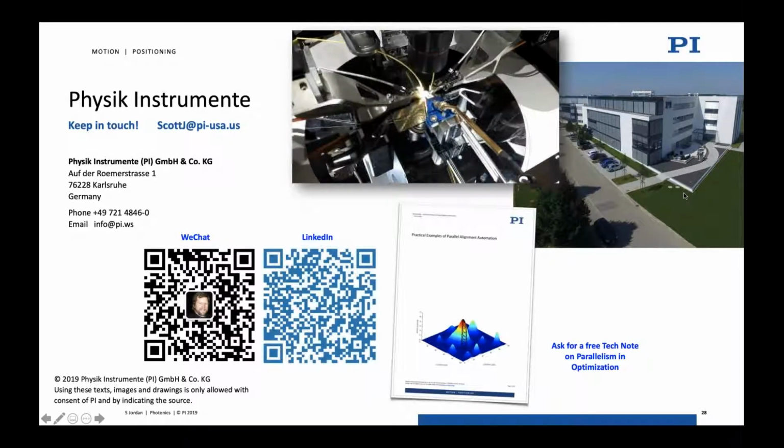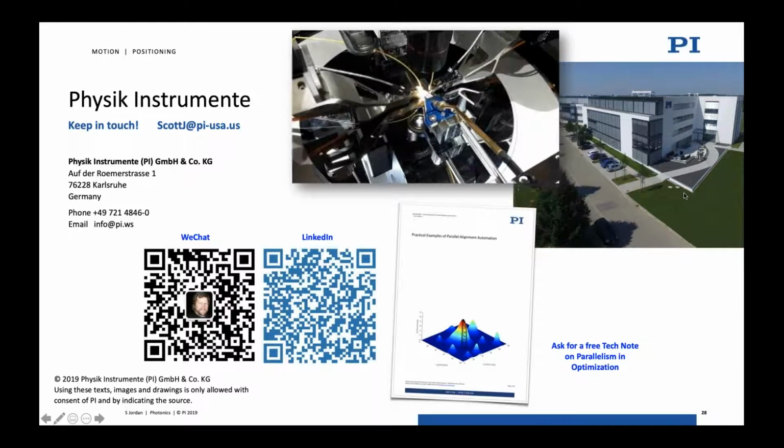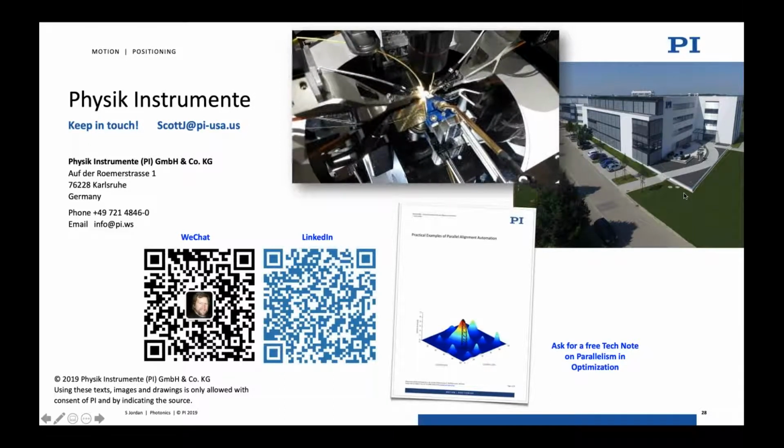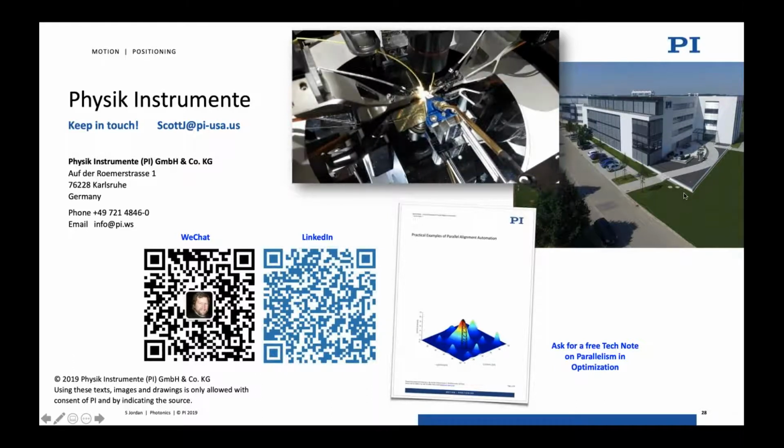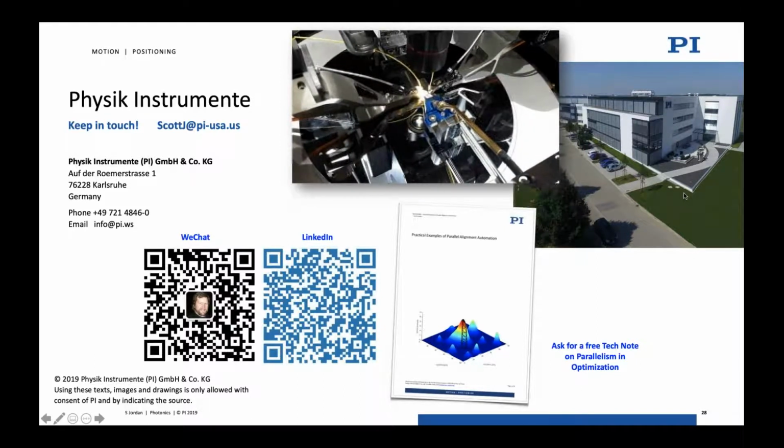So the bandwidth of the positioning devices is definitely a limiter. Physics is physics, but we get around that by using things like piezoelectric nanopositioning for the highest bandwidth requirements, which is typically the tracking. The XY is usually the most sensitive and the most compromised by motions and other degrees of freedom. So that's typically where we use the nanocube. You don't have to. You can do it all with the hexapod, but the nanocube really speeds things up, and most of our customers are really into saving money in their production. Time is money. Okay.